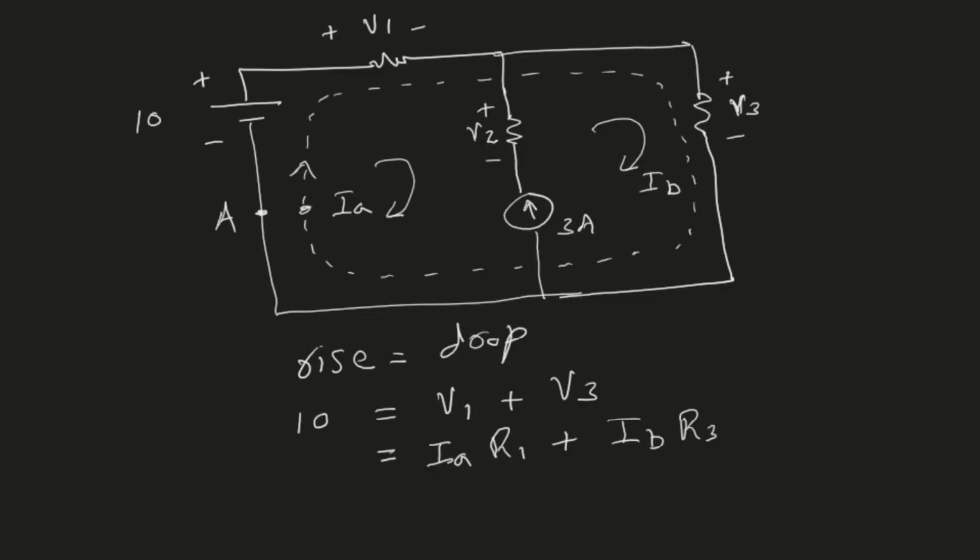And you can ask yourself, why did we have to do this? Why do I need different currents for the two resistors? Because we are now considering the outer loop. Why can't we assign a single mesh current to the big loop instead of the mesh currents that we have? We cannot do this because of the following reason. Let's say I assign one current. So that will say that the current that is flowing over here must be the same as the current that is flowing over here.